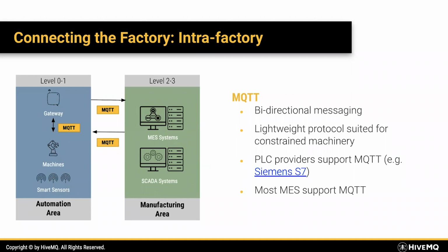So it's a bit opposite to OPC UA, which is rather bloated. MQTT is extremely lightweight by design. And most MES systems support MQTT nowadays. So if you're unsure, talk to your MES vendor. Most of the popular ones support this nowadays.